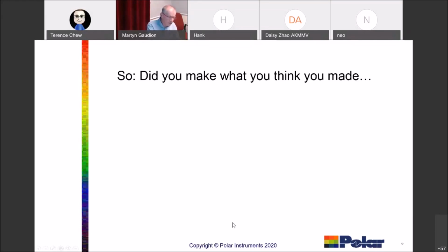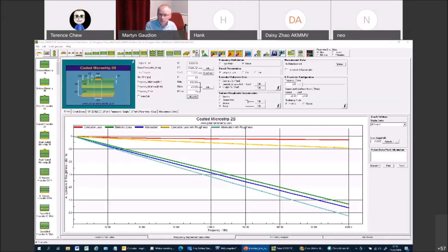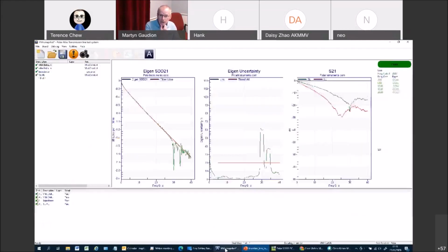We can run up the Atlas software and show you. See this here. So with Delta-L testing, it's very straightforward. It's really giving you a much better line fit than previous methods for insertion loss testing. What it does is it helps de-embed the effects of any vias or uncertainties within the trace. And so I'll just share the application.